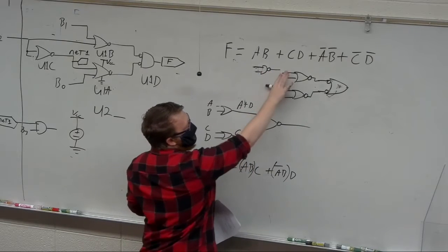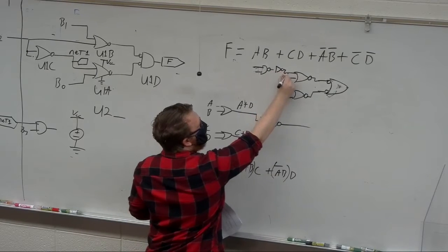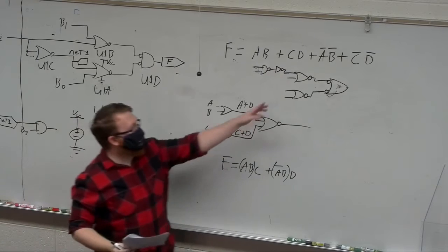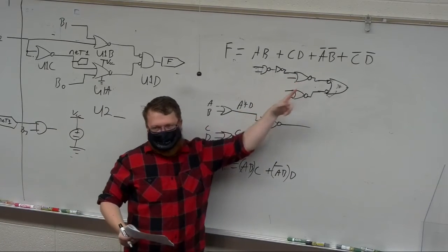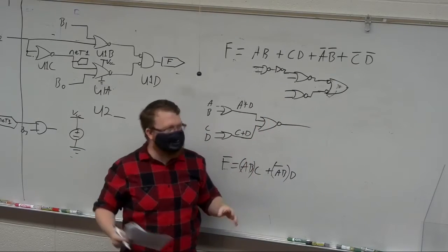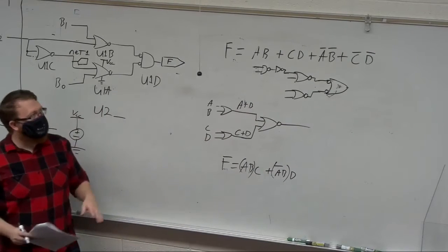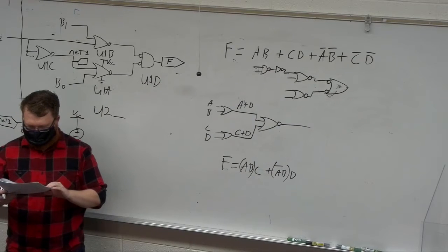The other option is to do that, but then you need an inverter here. I don't just want to draw a bubble here, because then I have bubble, bubble, bubble, and it's not really a NAND or a NOR. It's kind of some quasi weird thing. So it's better to explicitly call it the inverter. So that's how you design that circuit to get it into universal gates.